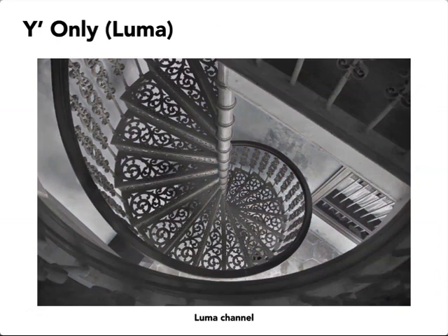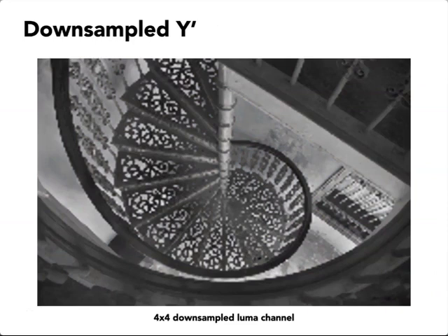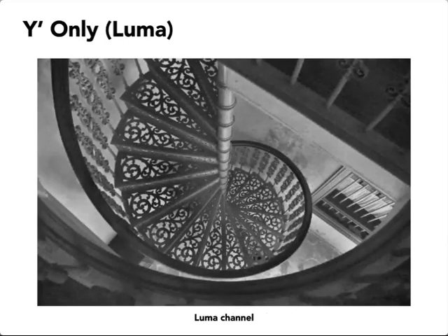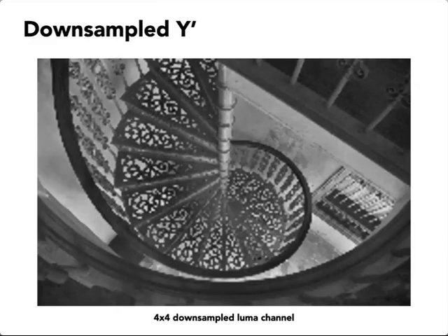If I downsampled it, and I'm going to downsample it quite extremely here, this is a 4x4 downsampling. So every 4x4 block of pixels, 16 pixels, averaged down to 1. I've averaged that and then displayed it here. So this is a pretty severe downsampling. And as you can tell, it's highly visible, right? We can clearly see the degradation in detail.